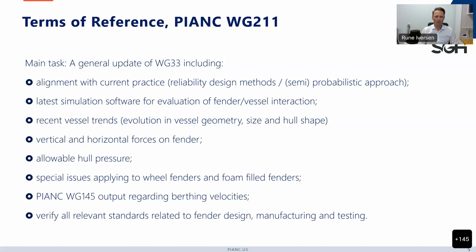We wanted to take into account recent trends in vessels, so evolutions in vessel geometry, vessel size, and hull shape. We wanted to take a close look at vertical and horizontal forces on fenders, allowable hull pressure, special issues applying to wheel fenders and foam film fenders. Also very important, take into account the output from PIANC Working Group 145 regarding berthing velocities, and then to verify all the relevant standards related to fender design, manufacturing, and testing.